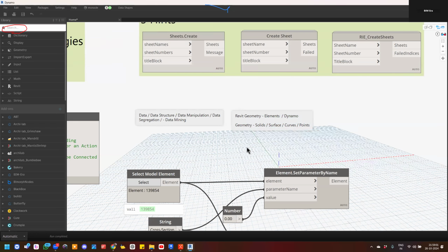Let me give you a simple example. Revit file and NWD file. What is the file storage of Revit? If it is 200 MB, the NWC file will be like 10 MB or 20 MB. Where 200 MB, where 2 MB. Because it's purely just like an interface. I mean, inside it doesn't have anything. It's just like a skull.